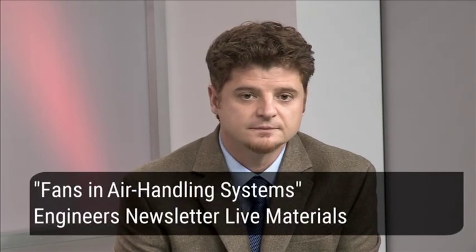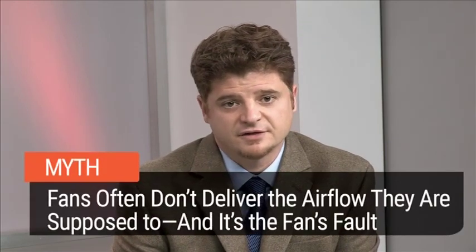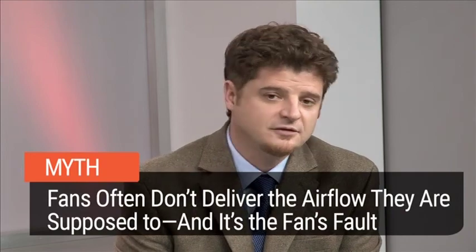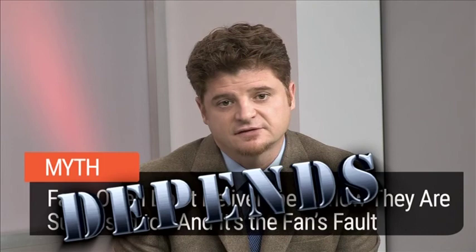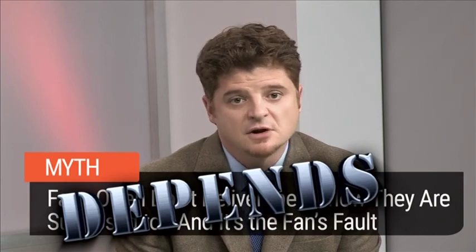So is it true that the fan's almost always at fault when it cannot deliver the airflow it's supposed to? The answer is, it depends. As we've seen, it's much more likely that the system pressure has been misestimated or hidden pressure losses like system effect are being unaccounted for. However, there are still many situations where the fan can be at fault.